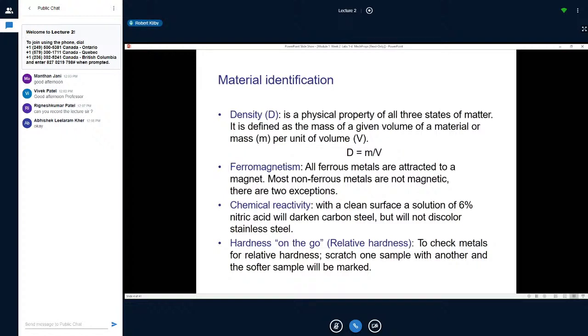That's a bit too big of a volume. So be very, very careful to make sure that the units you get when you're calculating densities give you the equivalent to what's in your reference that you have found. Because you need to refer it back to something that's published that says this is the density of steel, or this is the density of this particular steel, or aluminum, or whatever it is you're trying to find.